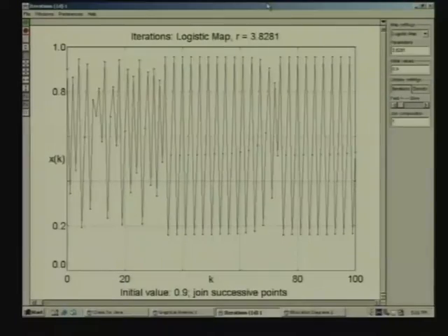The question is, how does that happen? In fact, in many experimental situations, you will find that the behavior is more or less chaotic. You can see that it is chaotic, but suddenly when you capture the waveform on the CRO screen, you find that it is a periodic behavior. What happened? It is just that for that small span of time for which you grabbed the waveform, at that point of time it was a periodic burst.